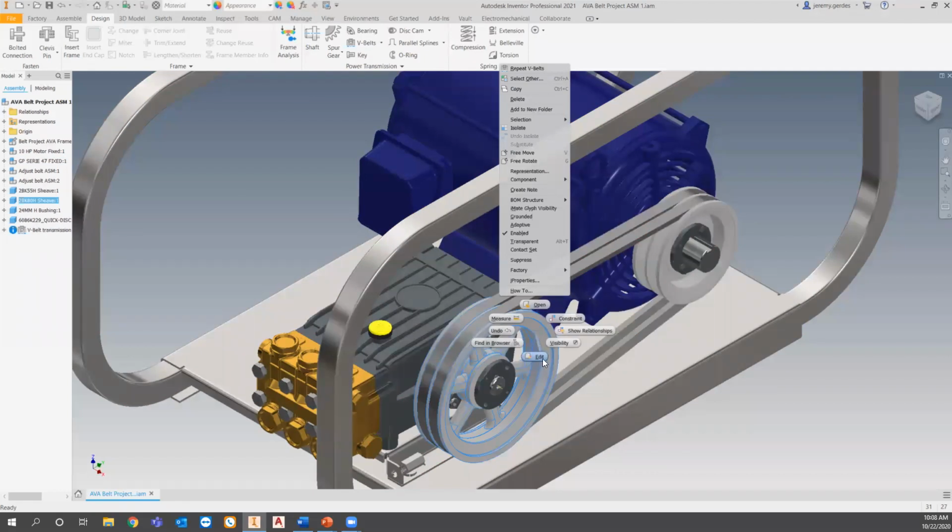Yes. In Inventor, it's going to calculate what the tensions of the belts need to be and what the starting position of the belts are to find the proper belt length for your application. And since this pulley is fixed onto the pump and the pump's fixed at a certain distance, it's not recognizing that that is an adjustable pulley. So it's not wanting to get all the data for its calculations correct.